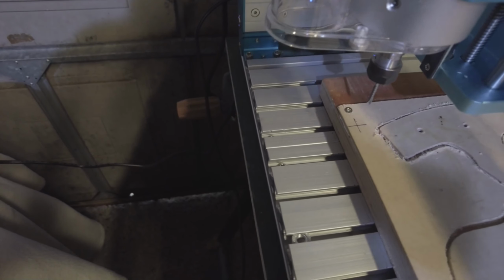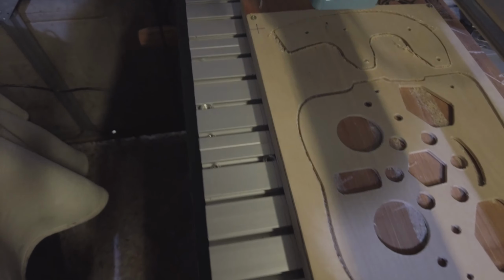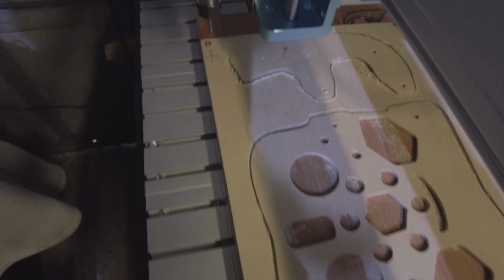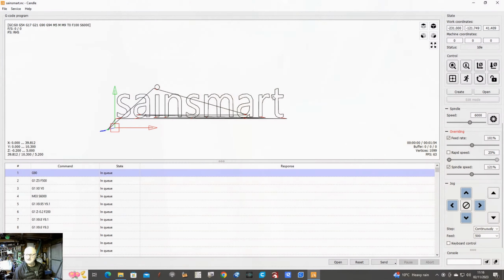There we are, we're roughly near enough. This is just to show you what happened. Right, we've loaded that program. The spindle won't be running, and you've already zeroed touched off with the probe, so we don't have to do that. That would be your Z-probe if you were doing it normally with a piece of paper, but because we use a touch off probe, that's already done.